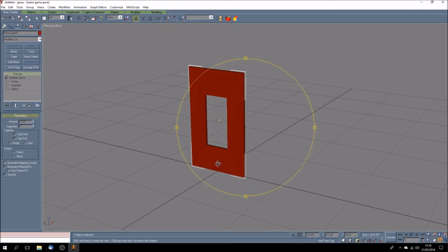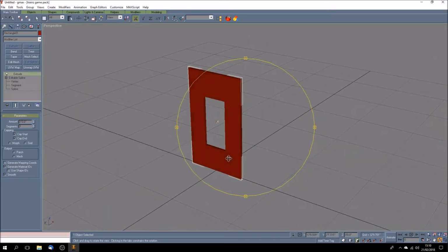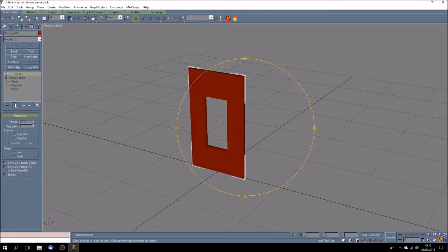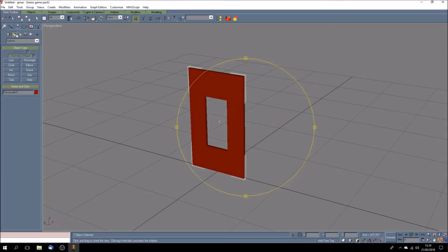If we wanted to, I'm not going to do it, we could bring in a texture of brickwork, just like we did with the box with the planks, and texture that wall. But because it's 50 feet high, remember, you've got to really tile the bricks all the way along, depending on the size of your texture, to get a proper effect, and that's where you can fall into the trap of making it look like some sort of tartan effect, you know, repeating tiles. So your textures are really important. But that shows you how useful this second type of mesh, splines, really is.